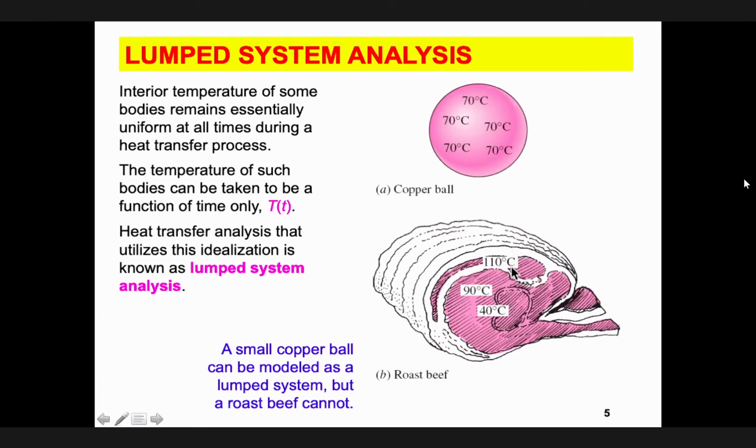Probably if you're trying to put this in your oven when you're cooking, the surface, the top, is 110 degrees because it's in the oven. It takes some time for the energy to transfer to the meat to get to the center. Designing a stove is by itself an art, okay? There has been a lot of research on how to design it, creating convective and radiation heat transfer so that you don't burn the top. You would like a balance between convective heat transfer here and here. That's why they ask you what you are cooking, because when you're setting up, you're trying to balance between this resistance here and this resistance here.